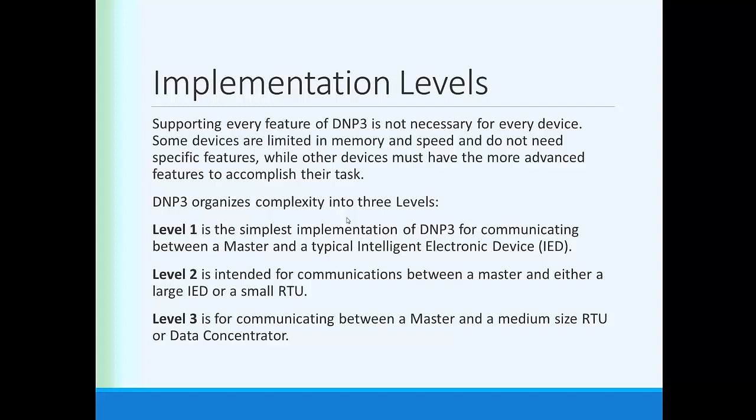Typically, level 3, you're only talking about RTUs and SCADA masters. Things that actually poll other devices have to have level 3 compliance. But level 1 and level 2 really come down to different subsets of functionality that are supported by the outstation, by the meter, by the IED.